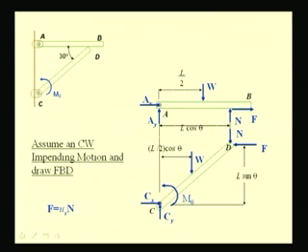So, we see that we have a total of 2 unknowns here and 2 unknowns here, 4 plus 2, that is 6 unknowns in this equation, and we have additionally one moment which is also unknown. So, totaling to 7 unknowns, but we have only 2 free body diagrams. So, which results in 6 equations only.